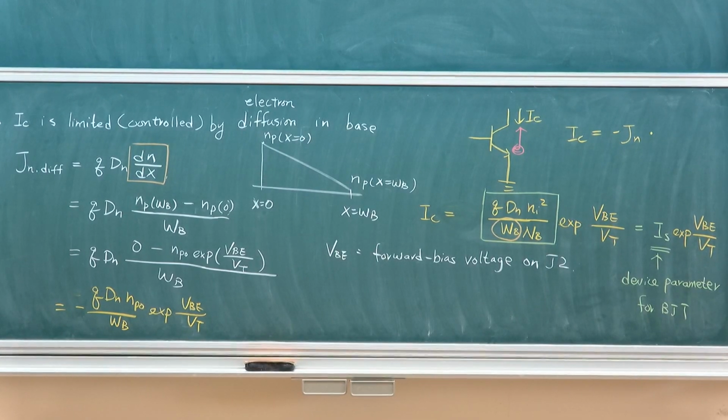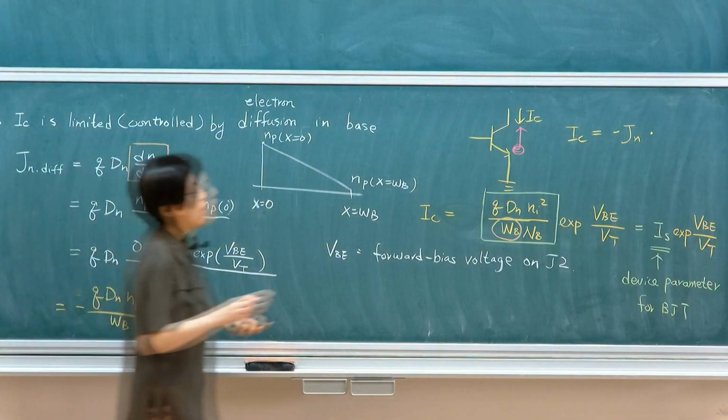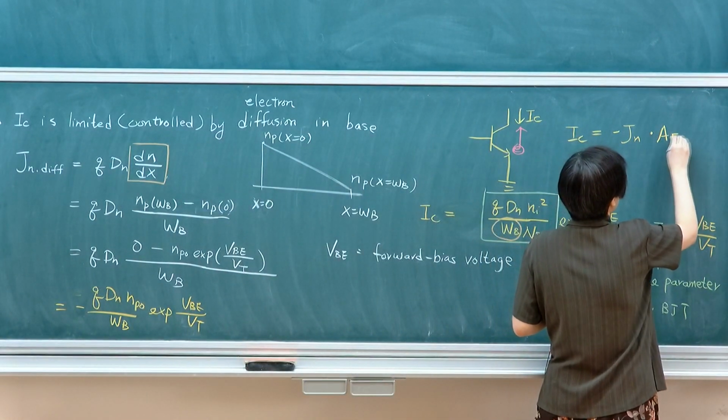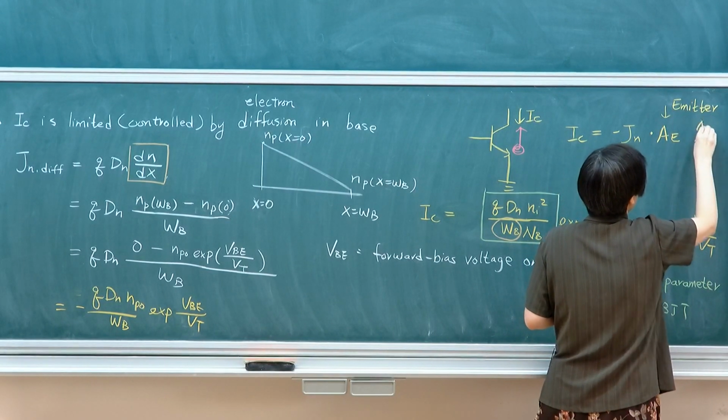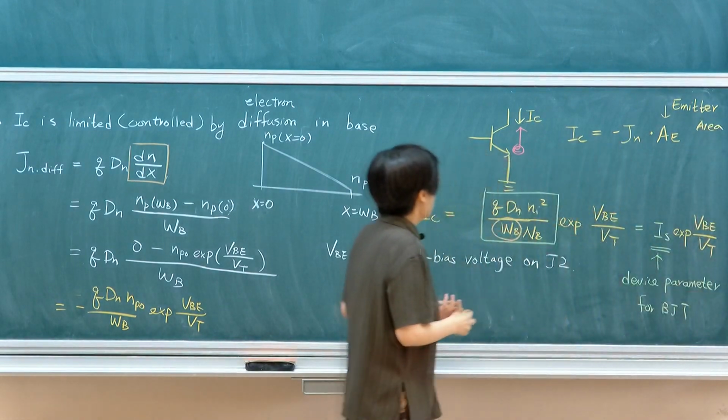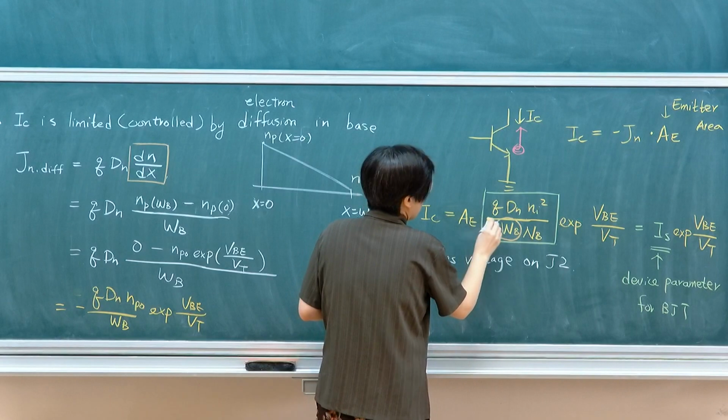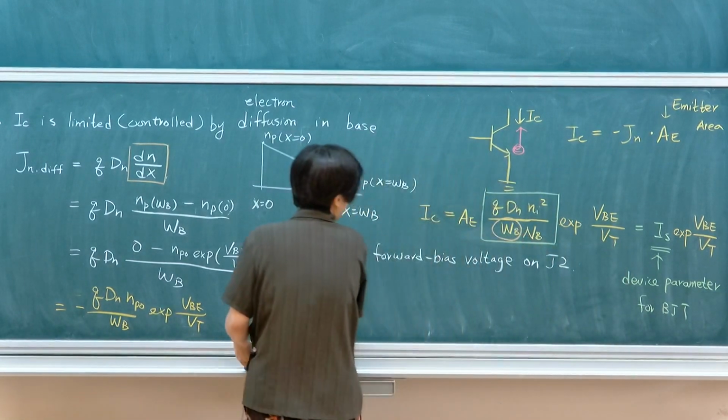For a diode, it's pretty easy because you have only one junction. But we have two junctions, so which one defines my cross-sectional area? Remember? What should I put in? The area of the emitter or collector or base. Emitter, correct? So it's AE. This is the emitter area, because the emitter defines your actual active area. So then I'm lumping. I need to lump this in, sorry.